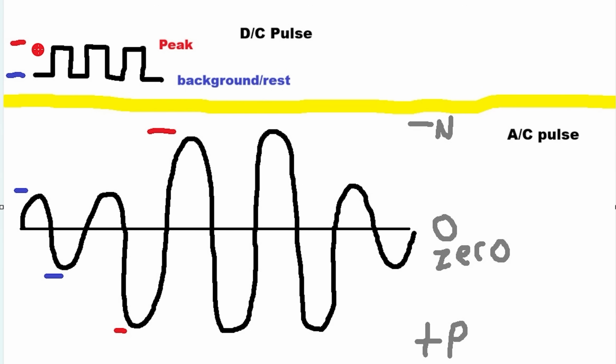With most pulse programs, you can change how many times per second it pulses. So you could have like 33 times per second, or you could have it once every 2 or 3 seconds. So you can typically fully adjust that. And then you can also adjust the peak time. Like you see here on this waveform, the more time you put on the time it spends at peak, the less time is available for resting. So more or less it will spend more time at high output, less time at low output.